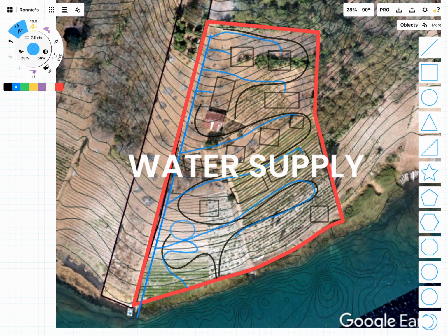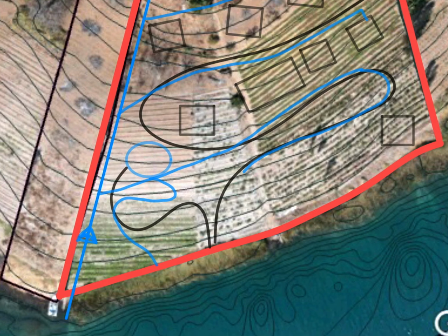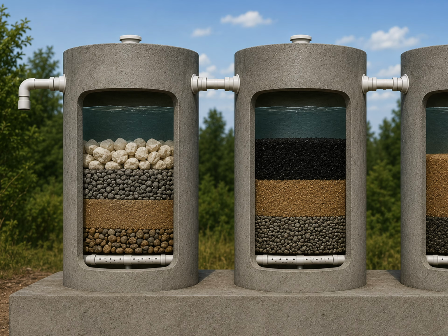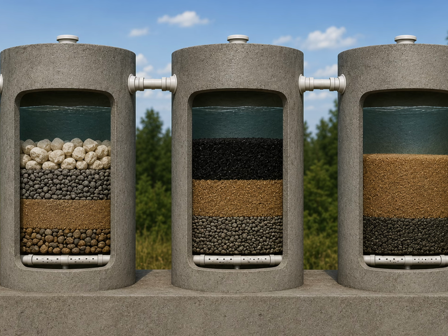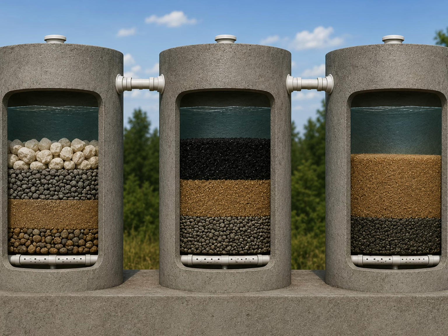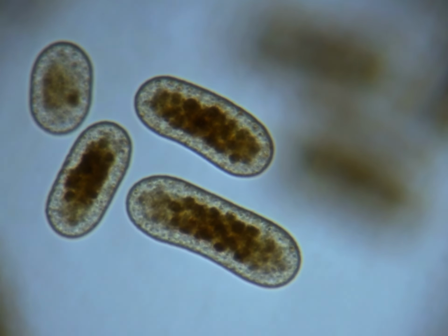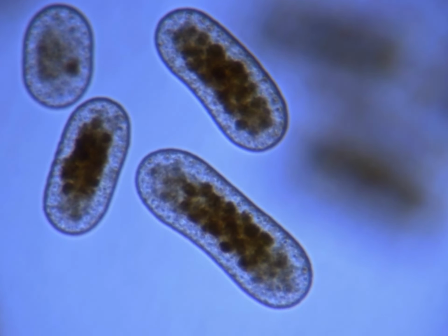Water supply. Solar pumps water up from the lake to filter it. 3 ferro cement tanks at the top of the property. Tank 1. Limestone for pH, drops out heavy metals. Tank 2, rocks and sand. Tank 3, clay. Then back down to the houses, each with its own UV filter for drinking.